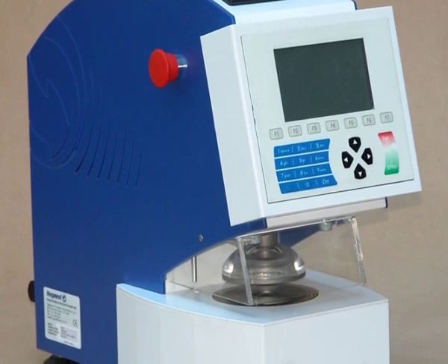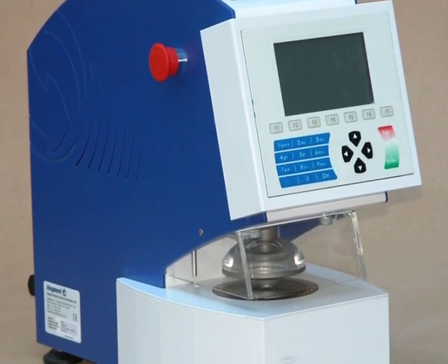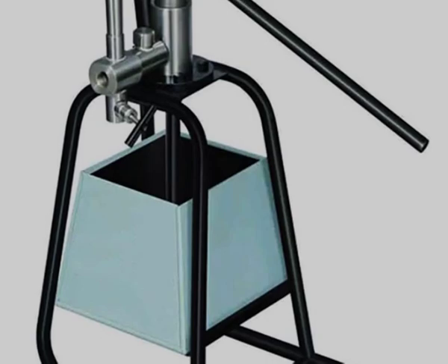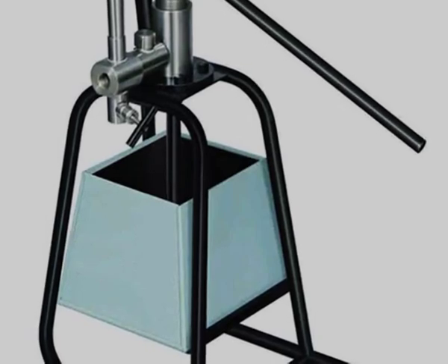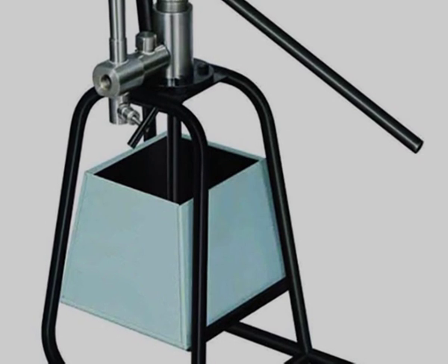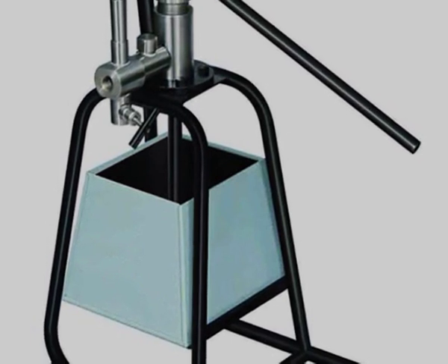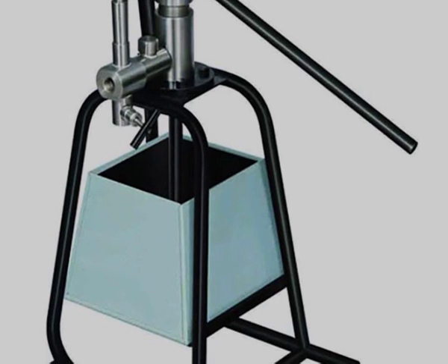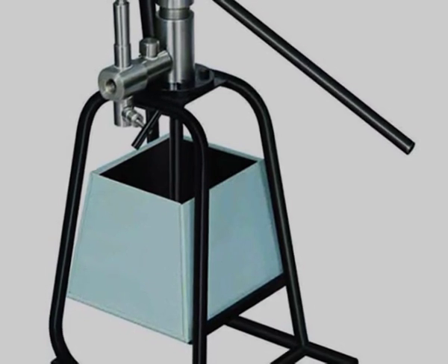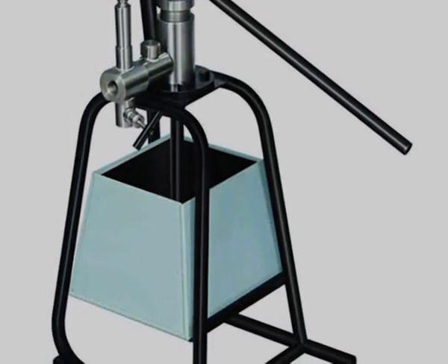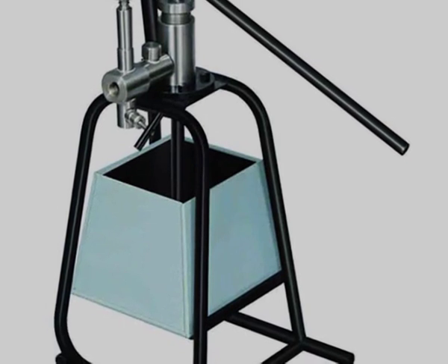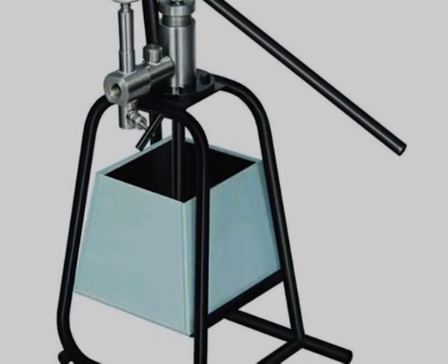The test piece is placed into contact with a circular diaphragm, the test piece being clamped around the periphery but free in the center to bulge with the diaphragm. Hydraulic pressure is applied to the diaphragm, bulging it until the test piece bursts. This denotes the general strength of the test piece.